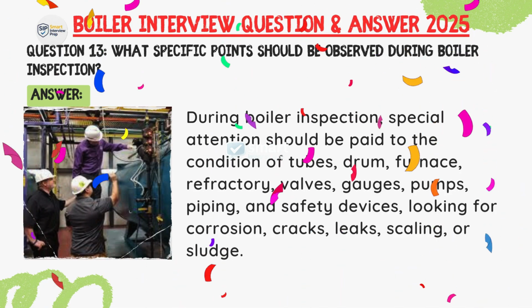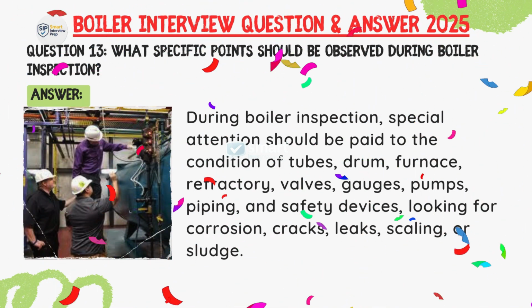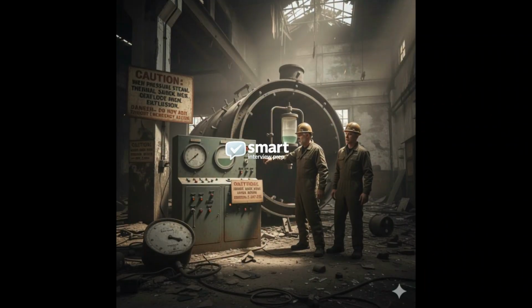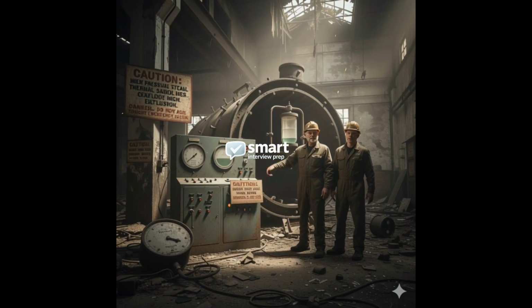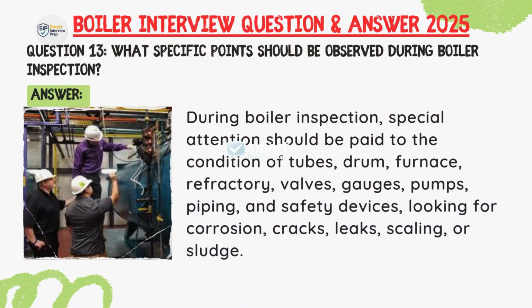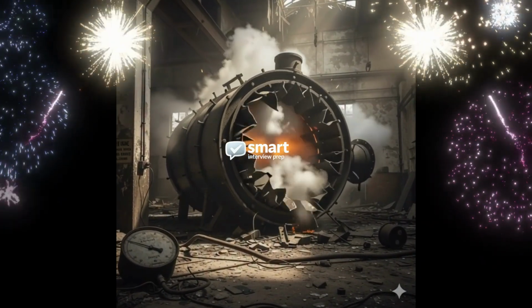Question: What specific points should be observed during boiler inspection? Answer: During boiler inspection, special attention should be paid to the condition of tubes, drum, furnace, refractory, valves, gauges, pumps, piping, and safety devices, looking for corrosion, cracks, leaks, sealing problems, or sludge.